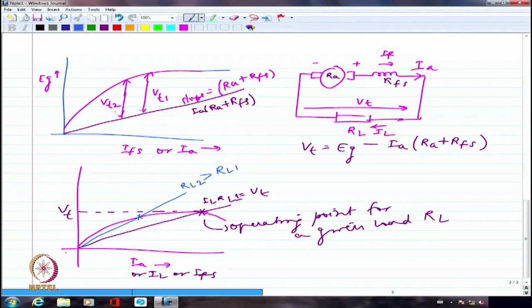What he is asking is, if the voltage is shown to be flat, the saturation has been attained, then after that itself it should start dropping right away, because if the voltage is a constant, the IA RA drop is continuously increasing as my IA is increasing. So you should not have any flat portion at all. It should start dropping right away.